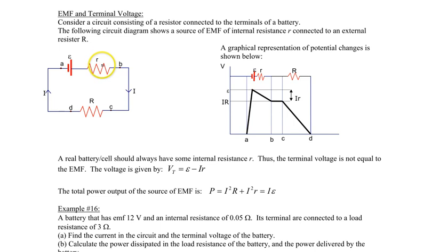If this resistance behaves according to Ohm's law, where r is constant, then the voltage lost across that resistance would be equal to V equals I times r. The terminal potential difference, or terminal voltage, is what you get if you hook up a voltmeter from A to B, essentially across the terminals of a battery. That voltage from A to B is equal to the EMF minus the voltage drop that is lost within the battery, and that is due to the internal resistance of the battery.